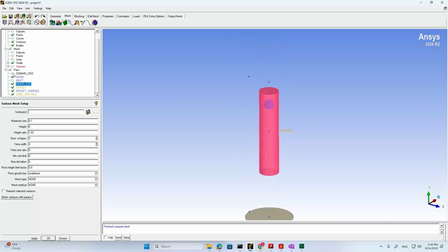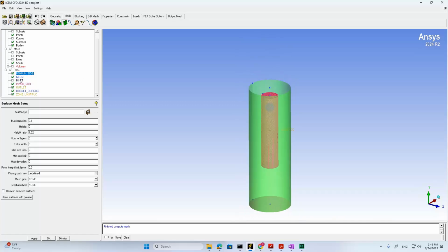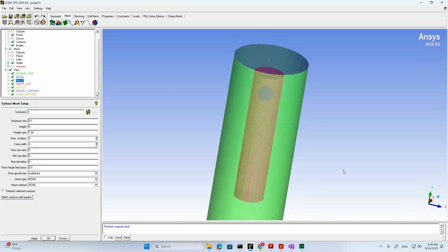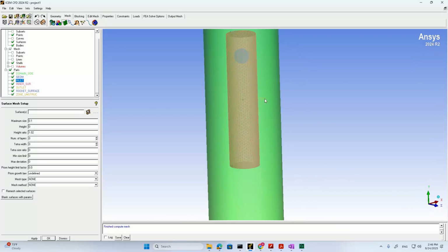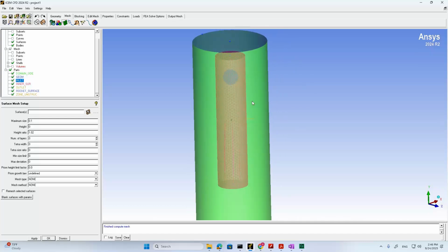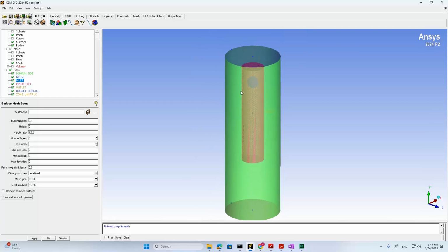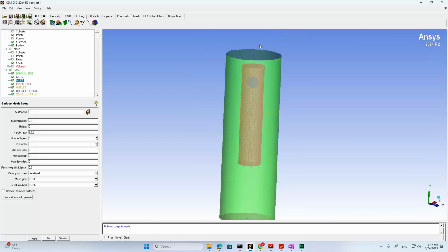Okay, then you can see I still don't have any mesh in this outer region, right, which is very normal because I didn't define any body point in this outer region, so the unstructured mesh will only grow and stop growing when it touches this inner cylinder surface. I don't want any such unstructured mesh in this outer region, okay, because I want a structure mesh there.